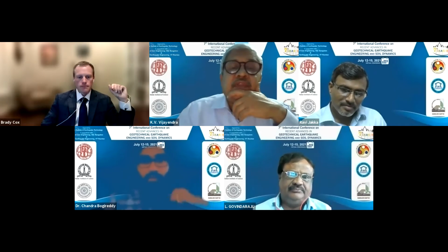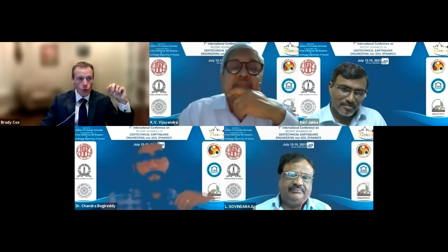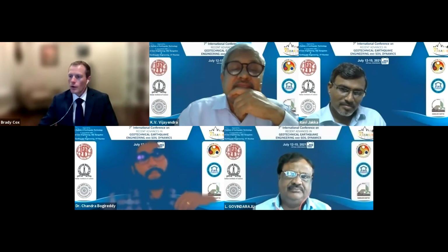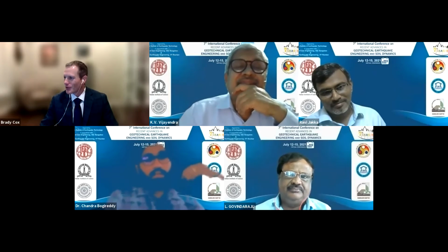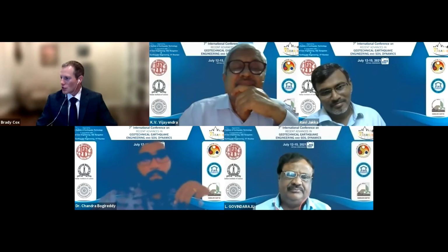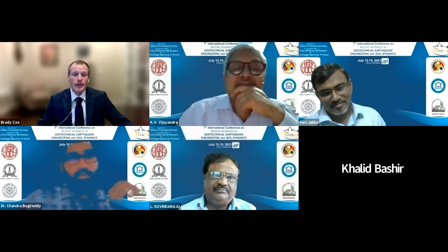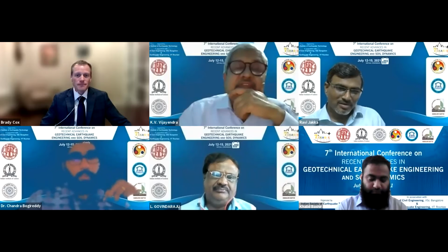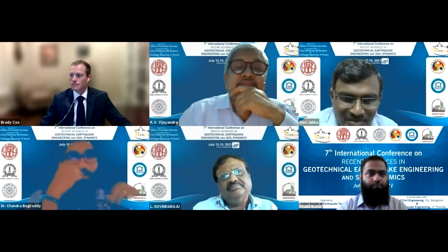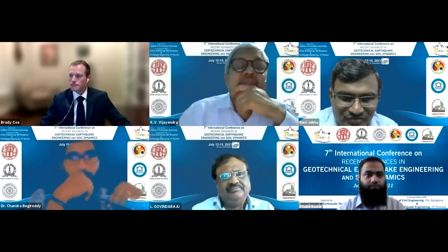What was the fourth or fifth mode frequency of the Treasure Island downhole array? The fourth mode frequency? Yeah. It's like less than 10 hertz. So I'll quickly go to those results and I'll tell you real quick. The fourth mode frequency at Treasure Island is only about 5 hertz. So it's a pretty soft site. It's a really soft site. Filtering has not affected those modes. That's correct.